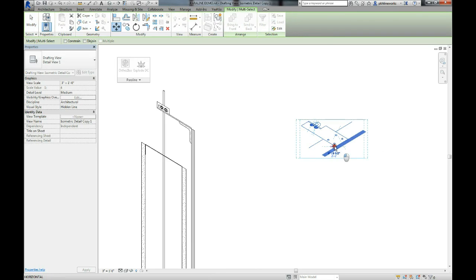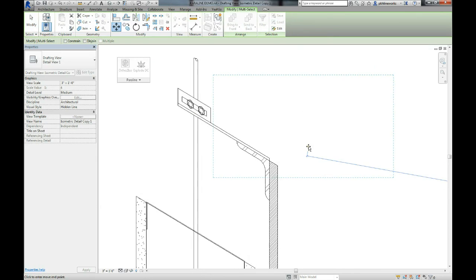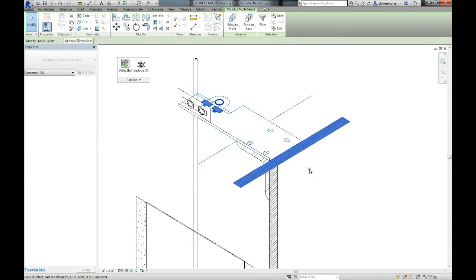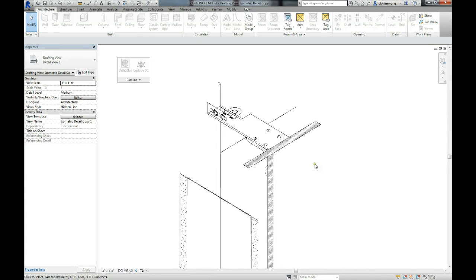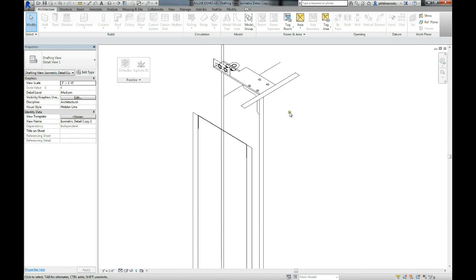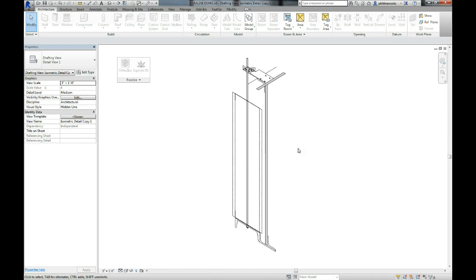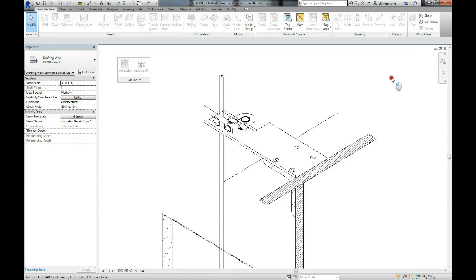And then we can begin to merge these two into a 3D isometric. You can begin to see our top view gives us depth, while our side view starts giving us height data that we can extrapolate from and convert this into a 3D isometric. So for this next part, I'm going to finish converting this top bracket assembly here into an isometric, but for the rest of the detail I'm just going to speed up the video so you can see very quickly how it works and just to see what to do.